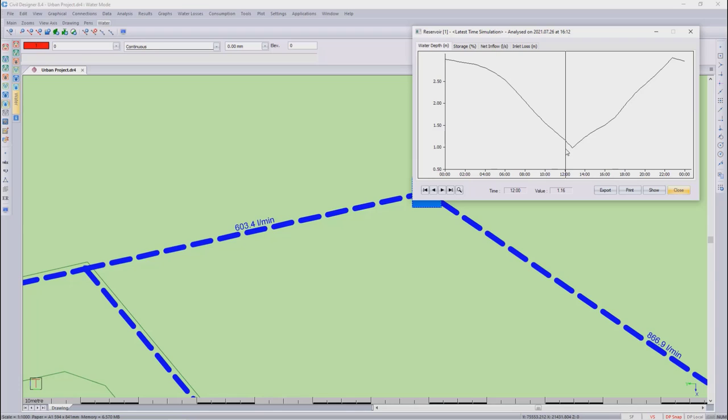enough storage space. So when it comes to the storage, you need to make sure that in some municipalities and some guidelines, the reservoir shouldn't get less than 65% full, and then the valve or the pump should switch on to start filling up the reservoir again.